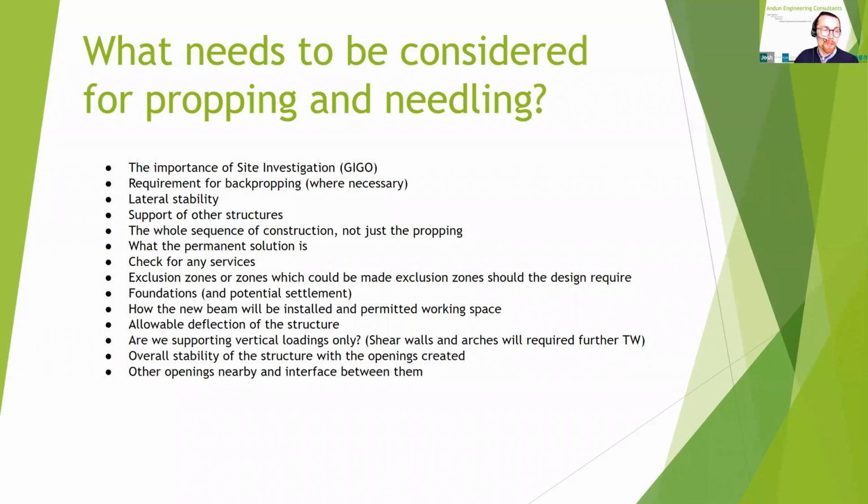The whole sequence of construction and not just the propping. This is very important for a couple of reasons. The first being loading on the temporary works. The system needs to be designed for the worst case loadings. Therefore, if the structure will be loaded by plant, material storage, snow, or potential vehicle strikes during its design life, and not just at the time of installation, then this needs to be considered at the design stage.